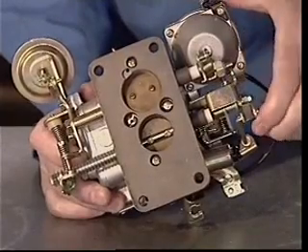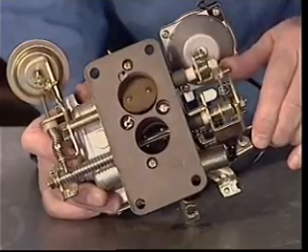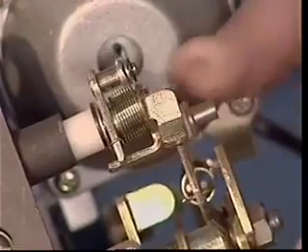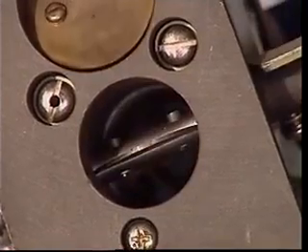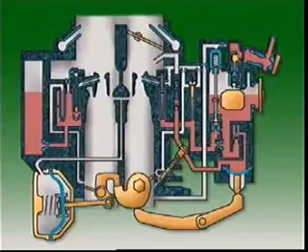The other basic design has throttles that open in 2 stages. It combines the 2 barrels to act as a single carburetor. The 2 stages combine good low-speed operation of a single barrel design with the extra airflow of 2 barrels.